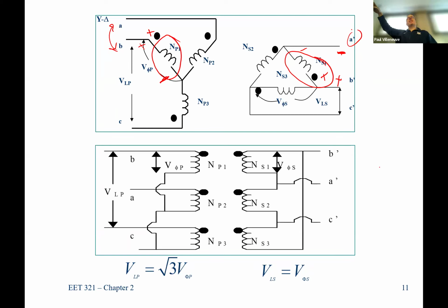But they gotta be consistent, because if you have the ability of connecting on another circuit and somehow closing them in, like here on campus, we have 2 feeds, top of campus, bottom of campus. We can't interconnect those because those 2 are never in phase with each other.